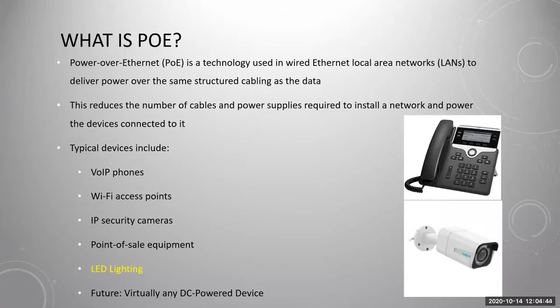Okay, so what is PoE? And really the basics of PoE, or power over Ethernet, is that you've got the integration of power and data on the same cable. So you're pushing DC power over your typical Cat5e, Cat6, Cat6a Ethernet cable, while also having that same data throughput that you would have over just a normal data cable. But now you've got power available too.